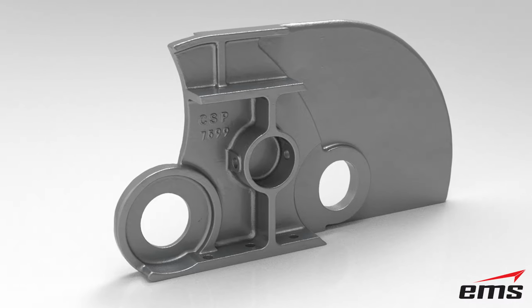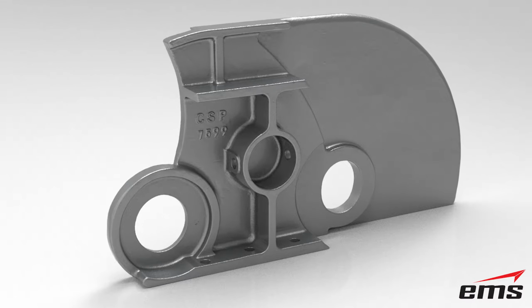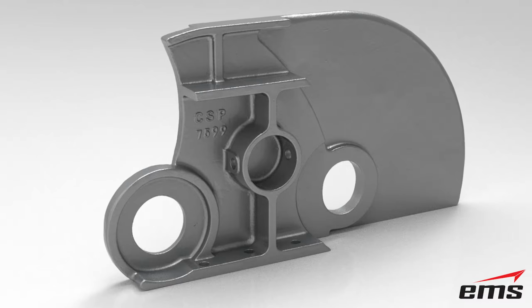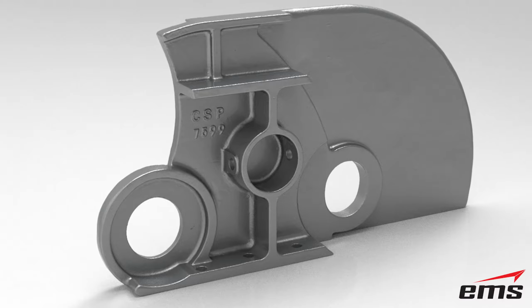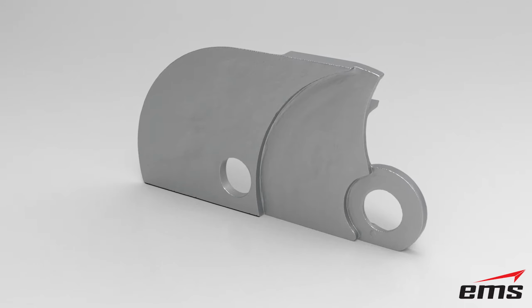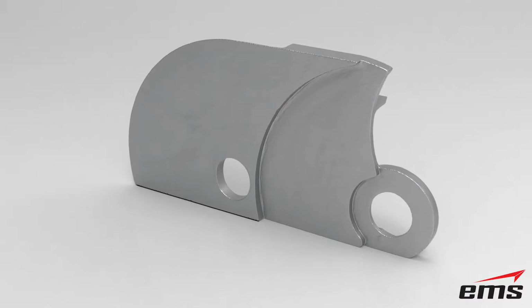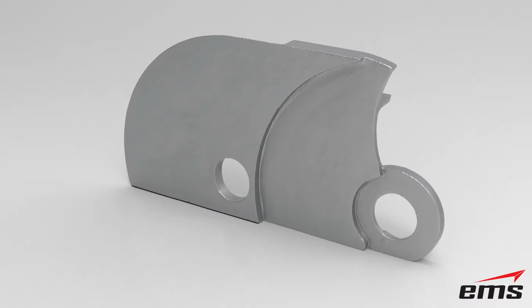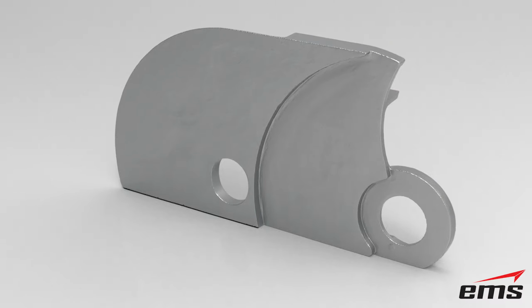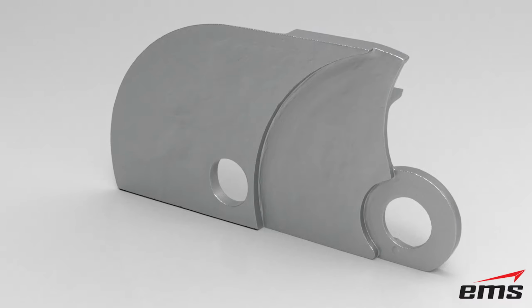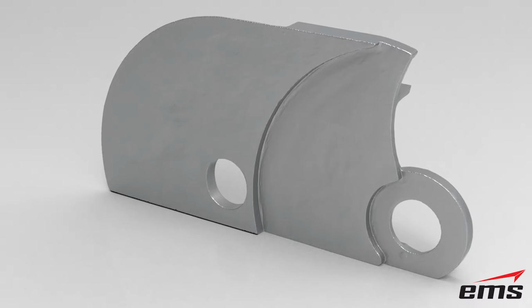software. Now, what is the Geomagic for SolidWorks software? It is a reverse engineering tool that runs right inside SolidWorks. So the real advantage of this software is it's very easy to learn and use if you already know SolidWorks. As you're going to see in this demo, there's really only a handful of commands that you need to learn to be able to model from 3D scan data, because SolidWorks does not allow you to import an STL file and really do much with it, and that's why you need an extension like Geomagic for SolidWorks, or